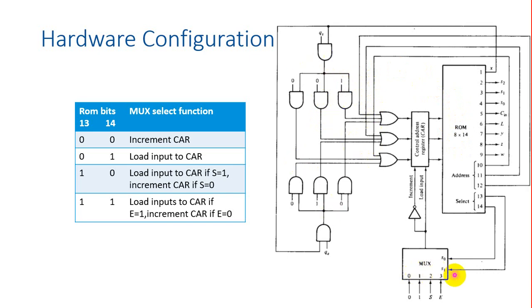This is the multiplexer that checks the branch control bit. You see, these are the 4 bits, zero bit, sign bit, overflow bit, the 4 bits of the flag register that you test with. And this is the control address register, and this is the incrementer.